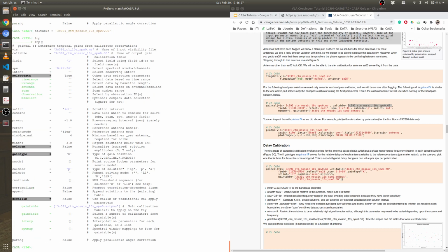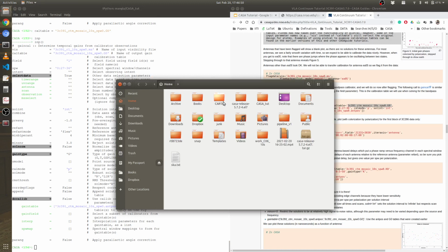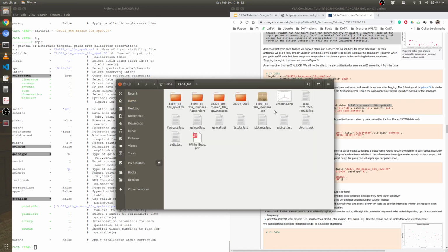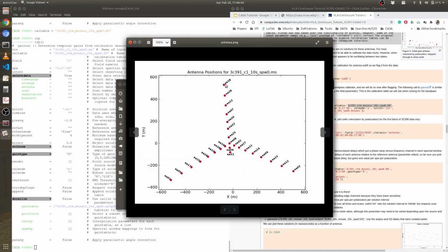You have to choose one reference antenna also. So you should choose your reference antenna such that the amplitude is most constant in time. So you should choose from in between. Let's go back to the antenna pattern that we have looked at.